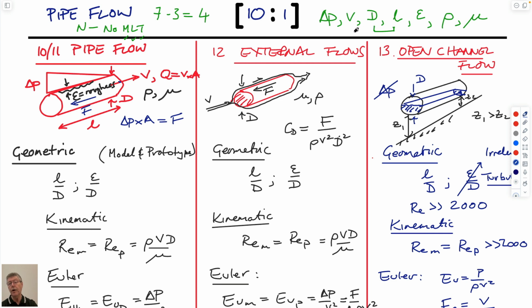those components would be. So for pipe flow, we have a viscosity of a fluid, we have a density of the fluid, we have a roughness of the pipe, we have the length of the pipe section that we're using, we have a diameter of the pipe, we have the average velocity of flow that's going down the pipe, which would be this, and we'd have a pressure drop. And let me change that pressure drop to write it as dP rather than delta P, because when we do this in another example, delta P is the pressure divided by the length, and I don't want it to be that.